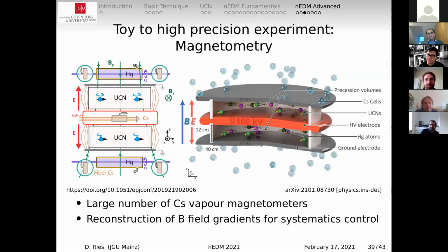And if you can use a precession frequency to measure a finite field, that's intrinsically significantly more accurate than typically the zero crossing of some resonance that you detect at zero field. Yeah, and on zero field magnetometry, you also have to remember that true zero typically only exists at one point. So it sounds nice in principle, but to use it in practice is not so obvious.